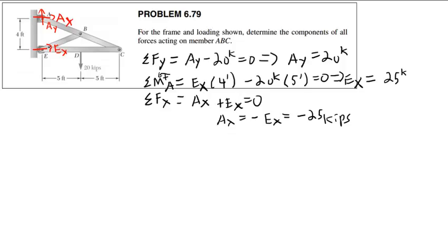One thing we can harness is that this member here, EB, is still going to demonstrate only one force because the conditions on trusses for pin-supported members still apply. If you have a generic member with pins on both ends, this member must carry either a tension load or a compression load, and that's it. So we can actually use that to our advantage.